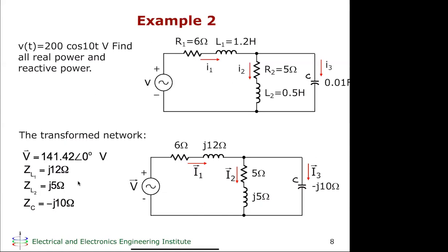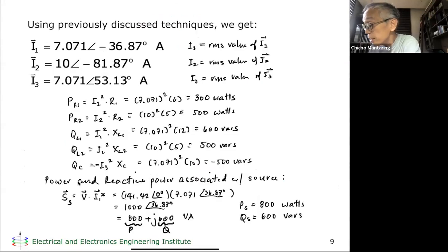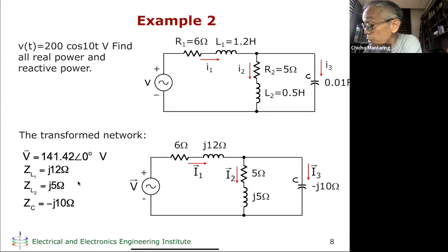Delivering, yeah. Because if the current is flowing out of the positive terminal, like in DC, that means as it is passing through the source, the charges that constitute the current are gaining energy. Therefore, this is delivering power. So the source is delivering. On the other hand, we know that these are passive elements and they will be absorbing.